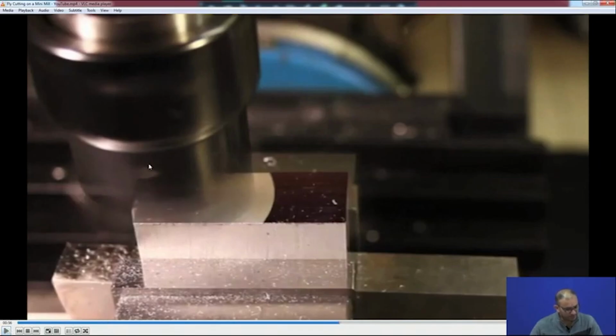And another thing, that this is the curvature. Now, if you put this particular cutting tool on a horizontal axis, then whatever is this curvature, you can create a concave surface on any circular component or the non-circular component. So, that is another advantage, because if you want to create a concave surface by a 3 axis milling machine, then you have to give a very small amount of x, y and z axis simultaneously, and that will create a lot of problem at the later stage, because this micro movement in x, y and z direction will create different type of tool marks.